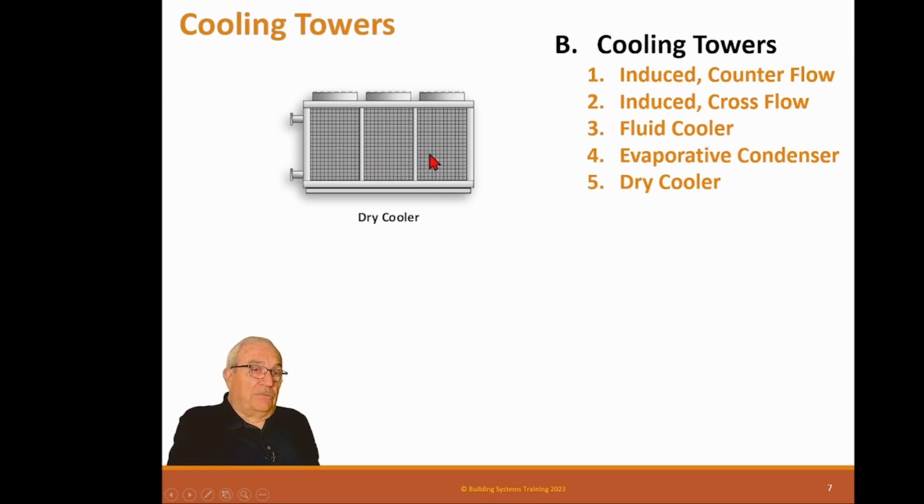And a lot of times we use these in buildings where they need to run the chiller in the wintertime, and it's cold outside, so these make excellent condensers, and they're real cheap, right? There's no water to them, and airflow is not that critical because we have really cold air. You might have 20-degree air out there and you're cooling it with that, so you have to modulate these fans down to not have that much air. So these are very effective.